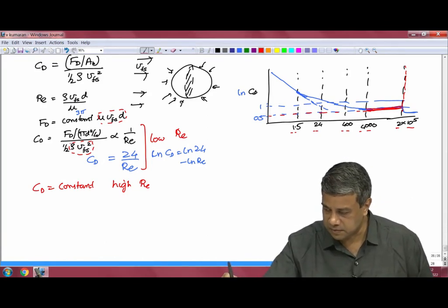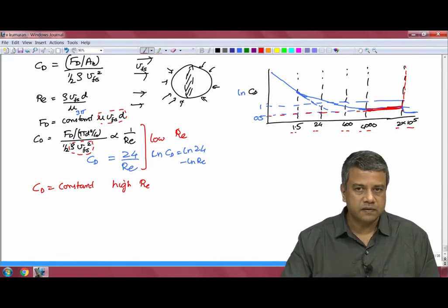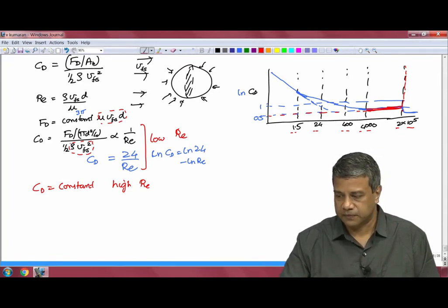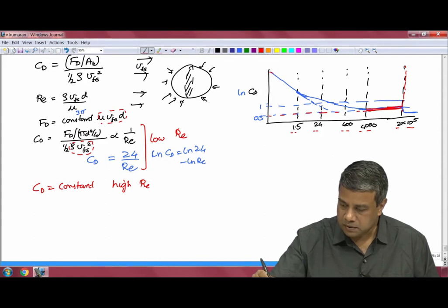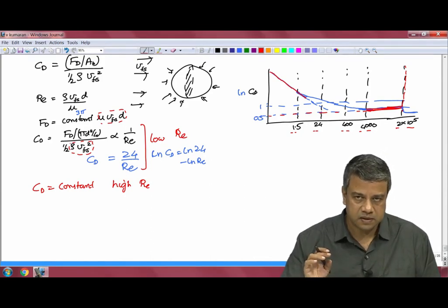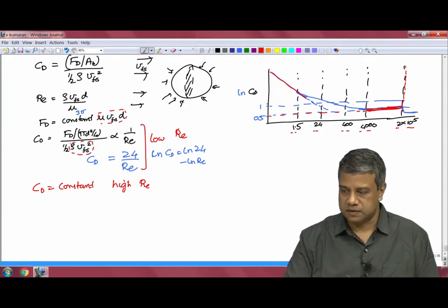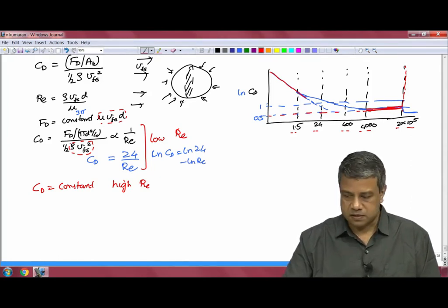If viscosity was not a parameter, then the drag coefficient has to be a constant. That constant value is about 0.5. Here it is about 1 over Re, as we would expect from dimensional analysis if drag was entirely viscous and density had no effect on the drag force. And in between there is a smooth transition.